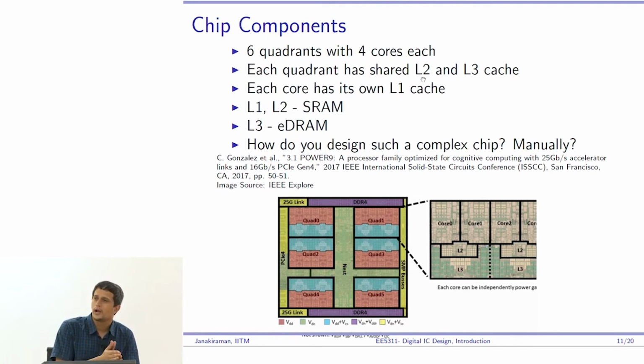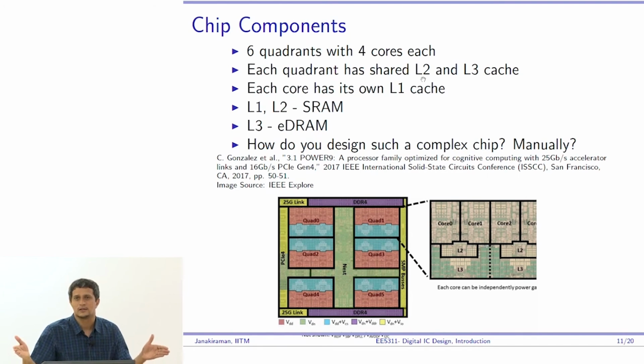people figured out that going outside to the DRAM and fetching data is extremely slow. You can't keep doing that. Therefore, you needed to have some faster access. But of course, you can't have access to all the data at one shot. You start doing something known as caching, right? And that's why you have a hierarchy of caches called L1, L2, L3, L4, and then the main memory. This basically grows in size, right? But becomes slower and slower as I go to the higher level of cache.